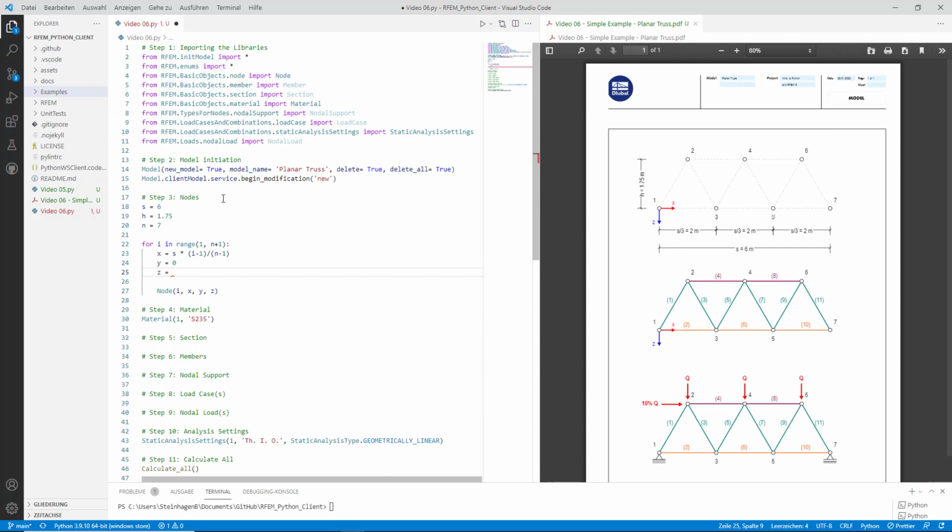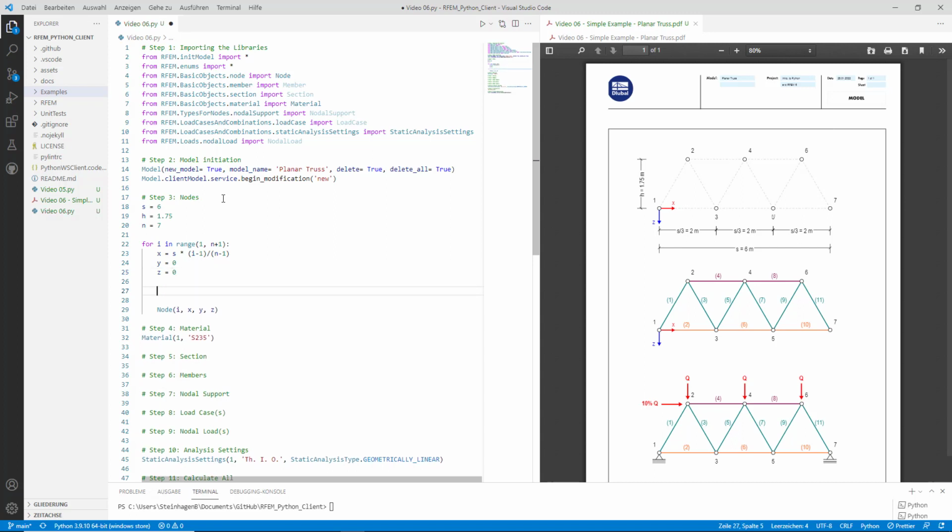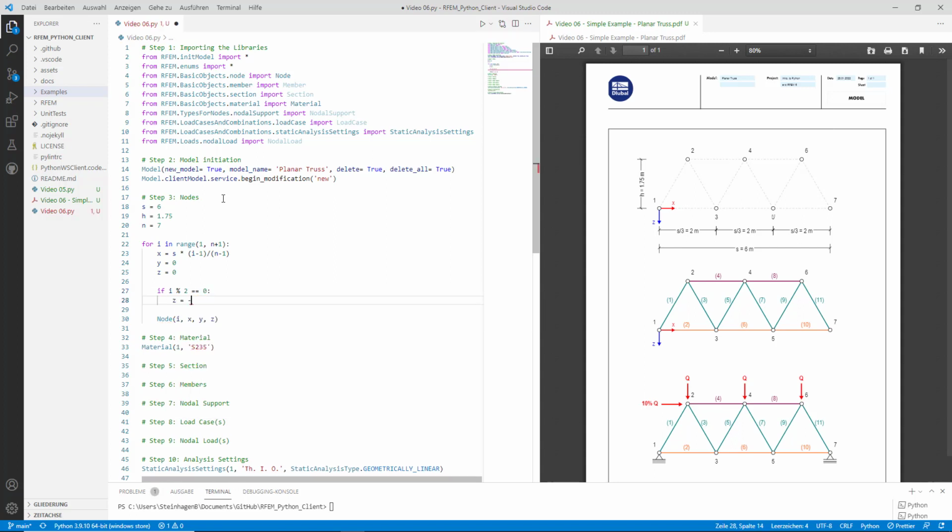In terms of our z coordinates, all odd numbered nodes have a z value of 0, while all even numbered nodes have a z value equal to the height of the truss. We can, by default, set all z values to 0 and manipulate the appropriate nodes by filtering for the even node numbers using the Python modulo operator.